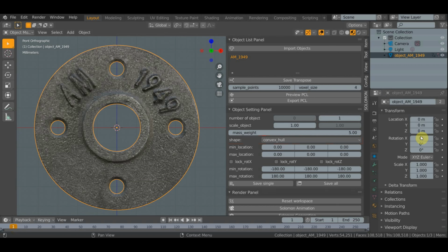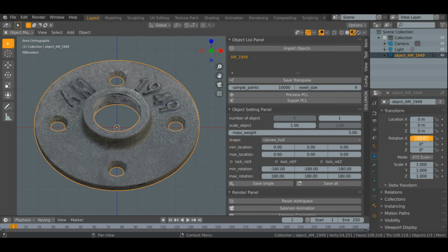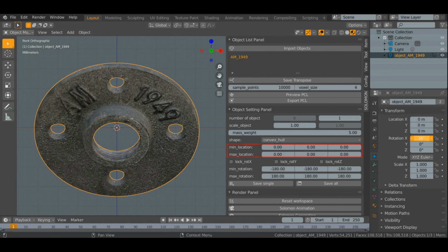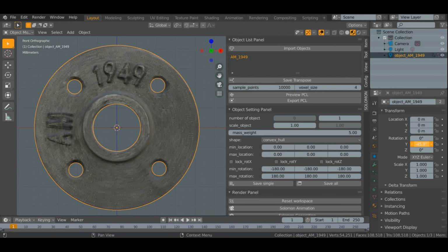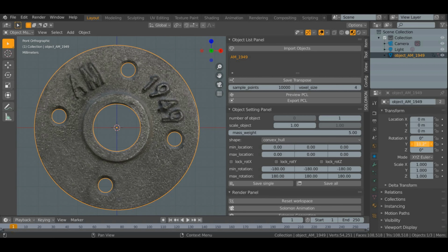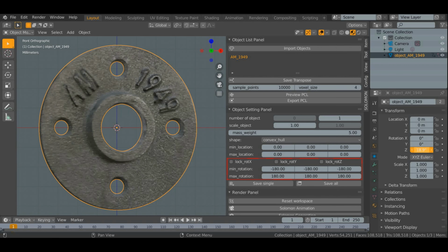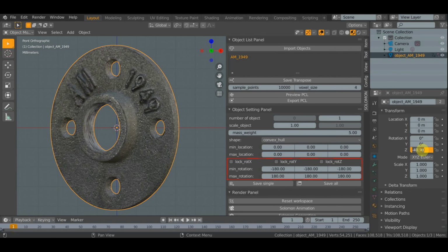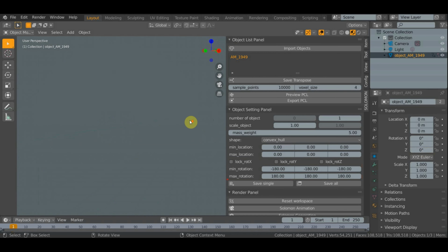Sometimes we have to delimit a specific region of the bin for a unique type of objects. Therefore, limiting the same region where we are going to place the objects in the simulation is a useful method to emulate the reality. Sometimes, the objects we want to pick are going to appear showing only one side of it, for example, only the front side. That is why we can lock the rotation of the object and obligate it to fall showing only one side, like the front side in my example.